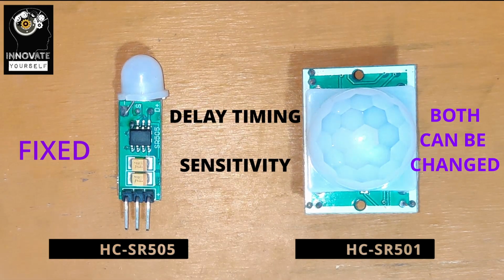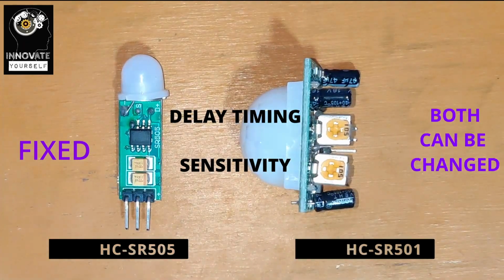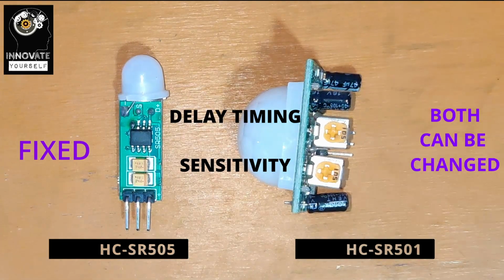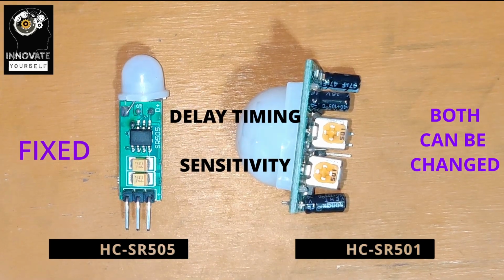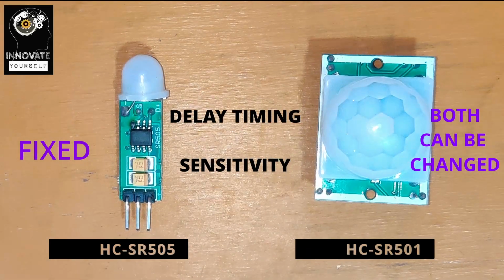How are you going to change that? Let me show you. Just turn it over. Here you can see that you have two variable resistors. You can just turn the knob, and accordingly you can change the timings as well as the sensitivity. So these are the two types of sensors.